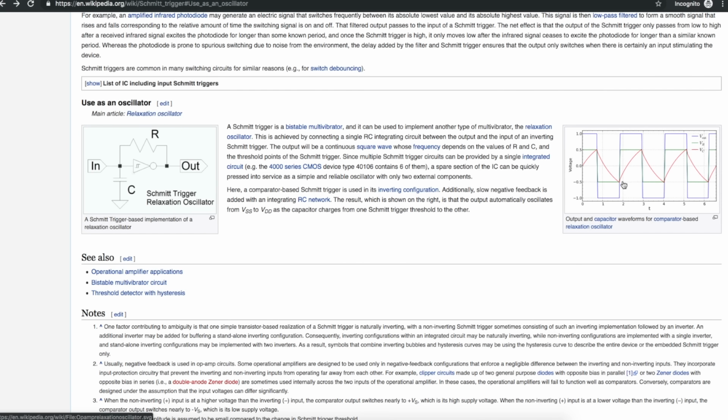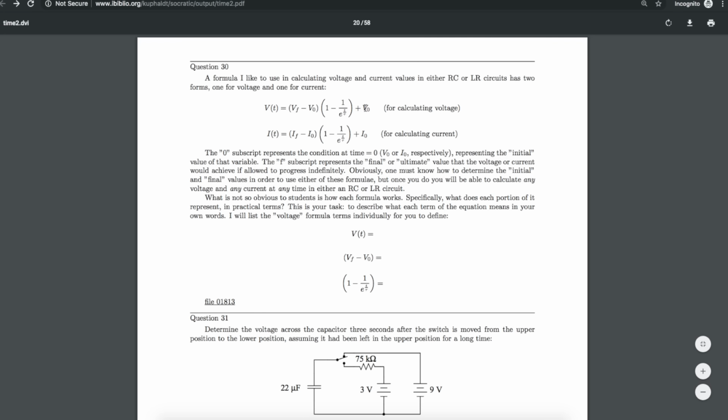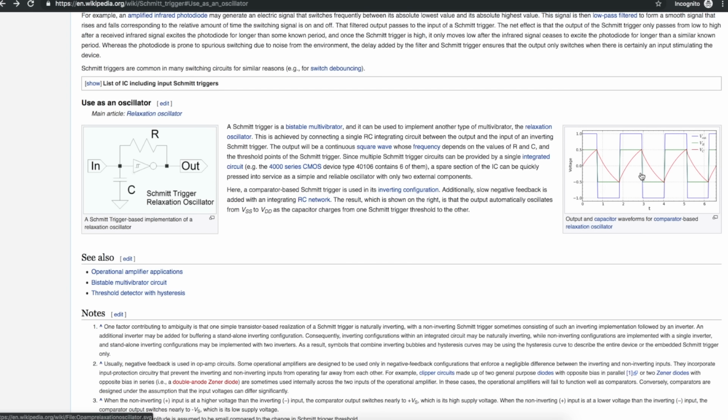If we start right here, we know the voltage here. It's whatever that lower threshold is on our gate. We know our target is going to be whatever the upper threshold is on the gate. We know that if we let it keep going, it gets to whatever the gate can output close to VCC, or discharging, we know if we let it keep going, it would try to get to whatever logic low is, close to ground. What we don't know is the time it takes to discharge or the time it takes to charge. So we use this equation, solve for that time for both charging and discharging, add those together, and that will give us the period of our signal. Then 1/that gives us our frequency.